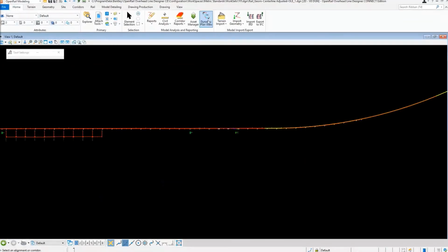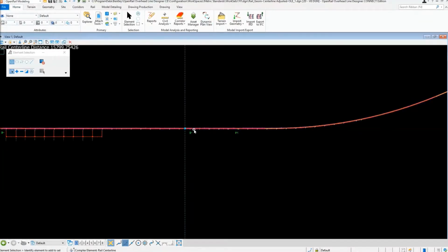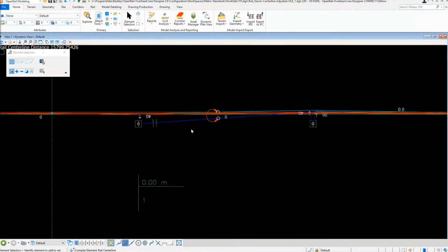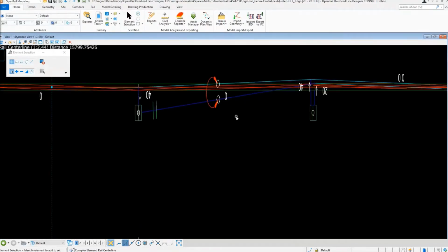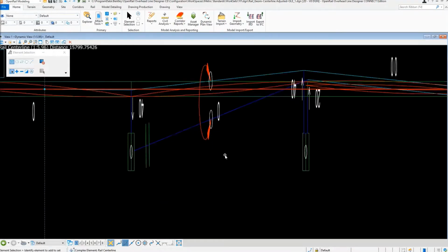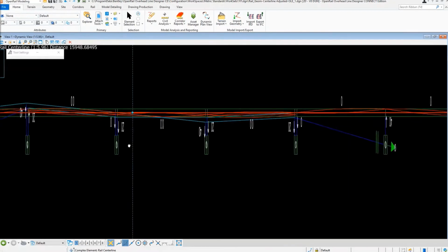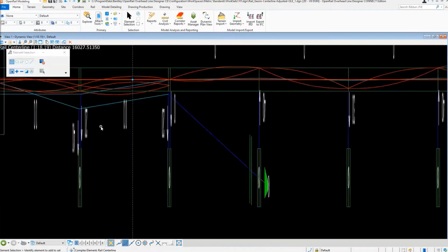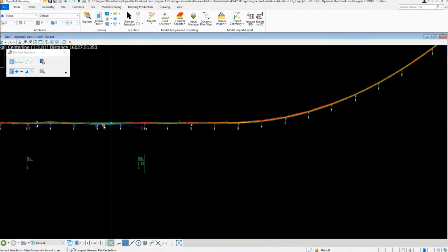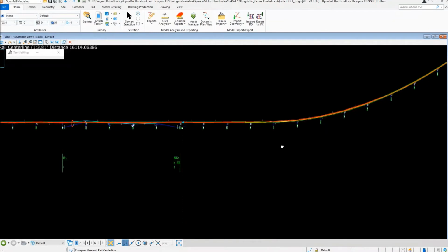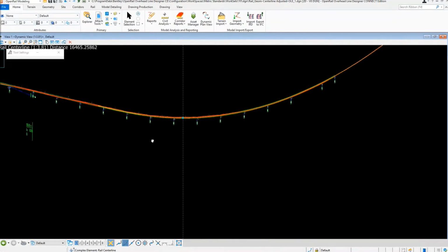This is just to show you a demo of how it appears within your real catenary system design. You can see the pantograph range is visible as you zoom in, and you can make sure, like over here there's a mistake, and you can make some design changes to ensure the wire falls within the pantograph range.